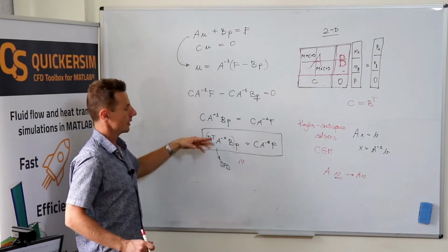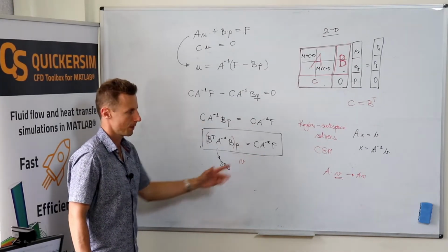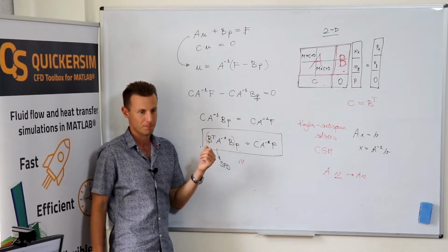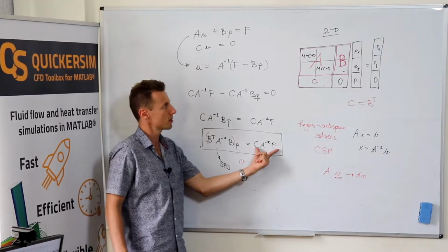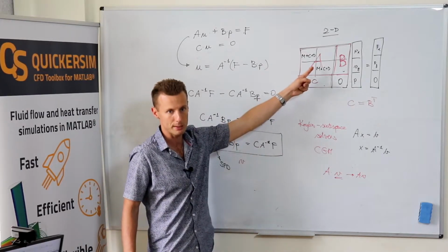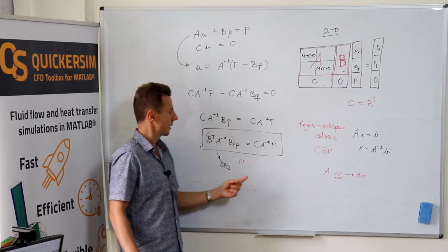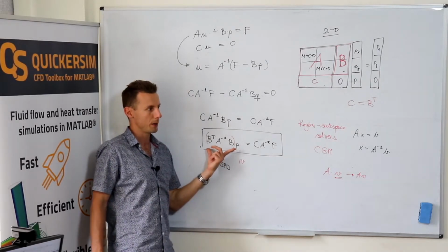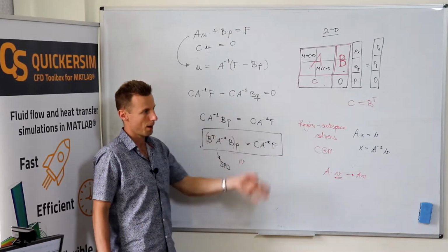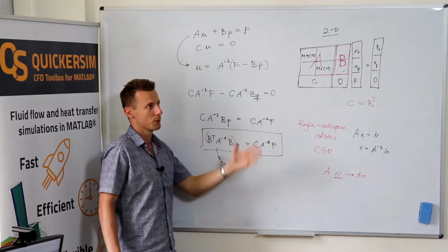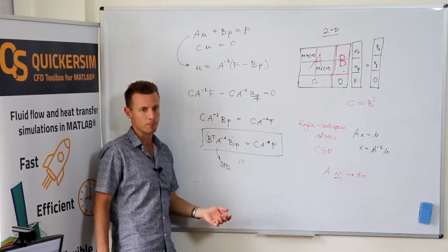And see, this would work and this would finish the solution procedure. What's the problem? Here, to generate the right-hand side, we need to solve the system of linear equations with the matrix A. We did it once. Okay, not a huge problem. What's the problem here? We need to run the conjugate gradient method that will do its iterations, typically 50 to a couple of hundred iterations for the real physical problem.